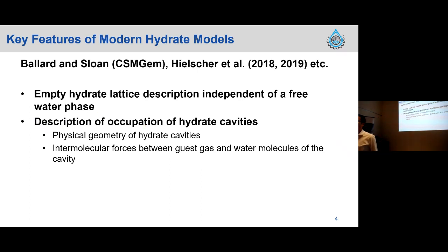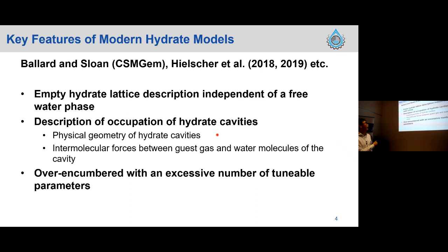And in terms of the features we're concerned about with hydrate modeling, there are two main parts. You have the empty hydrate lattice description that's independent of a free water phase. And secondly, we have a description of how the gas molecules actually occupy the hydrate cages. So we're looking at the physical geometry of the hydrates themselves, as well as the intermolecular forces between the gas and water molecules. What I'll be walking through today is the basis of these two models and how we've improved them, because they're currently over-encumbered with an excessive number of tunable parameters.